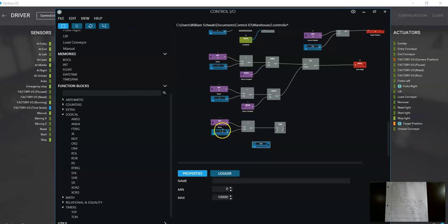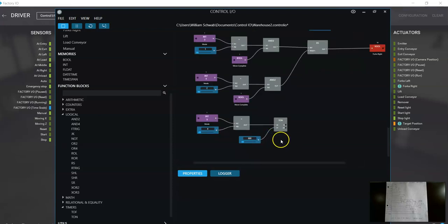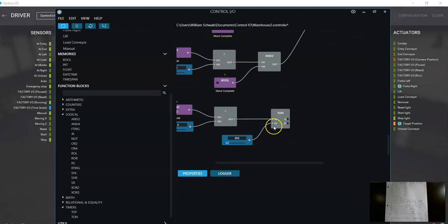so when you're putting these in, these are the modes, so they're just integers. When you're looking at the timers, these are in milliseconds. So right now this is 800 milliseconds. The other timer that was in there was like 2000, which is 2 seconds. So this will count out and put in a delay of 800 milliseconds.